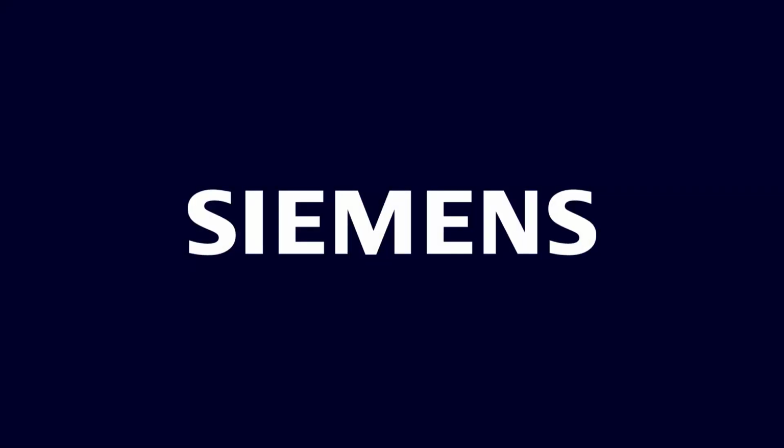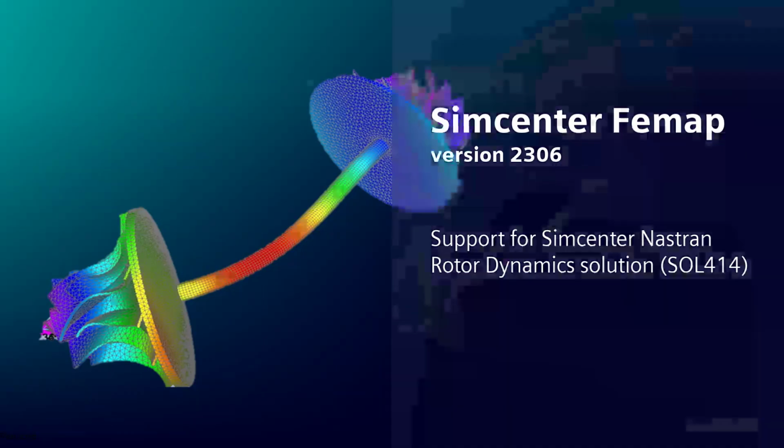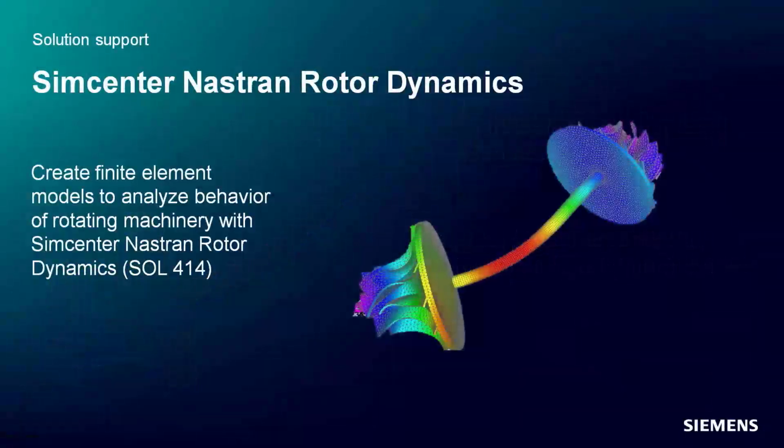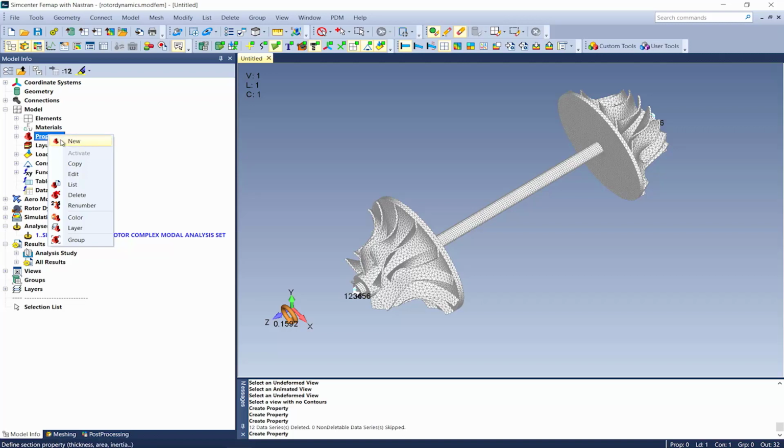Femap 2306 introduces extensive support for Simcenter Nastran's Rotor Dynamics solution sequence, Solution 414, which can be used to execute different analysis types, including maneuvers, normal modes, complex modes, harmonic response, and transient analysis of rotating structures. For rotor dynamics, 3 new element property types are supported.